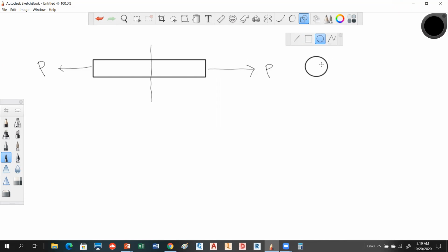So this represents the resisting area of what this is doing, and so the stress is developing along this right here. So this is my stress direction. Okay, so this is the resisting cross-sectional area of that. So this would be called axial stress, sometimes referred to as normal stress. But I want you to note the area of resistance right here is perpendicular to the direction that the force is. Okay, everybody understand that? That's really, really important. We good with that?